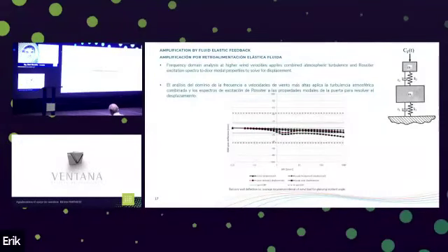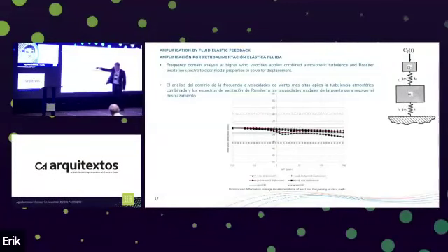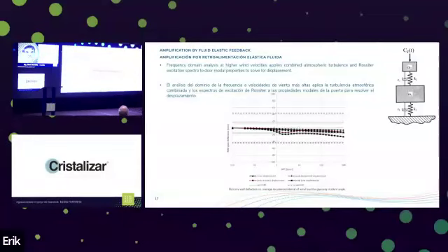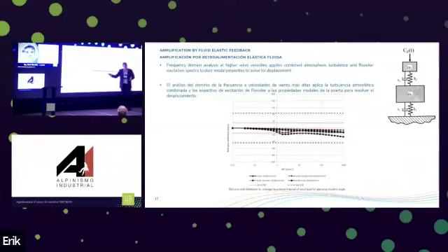And this is the result of a prediction on an example balcony I was showing earlier. We have mid-span deflection versus average recurrence interval, proportional to wind speed. So if you like, your sort of daily, weekly, yearly up to the 1,000-year return period on a log scale. And if you plot it out, you can see some curved deflection response. This is where we have the Rossiter excitation coinciding with the natural frequency of the balcony walls in this particular example.